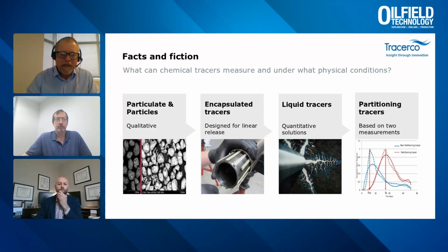Now, liquid tracers and gas phase tracers are the only quantitative solution under steady state condition. This is 40 years of proven technology evaluating communication between injectors and producers, now applied to unconventional wells and stimulations.